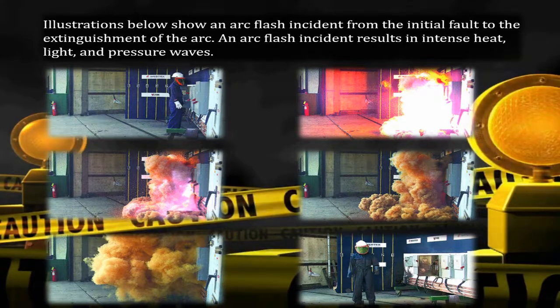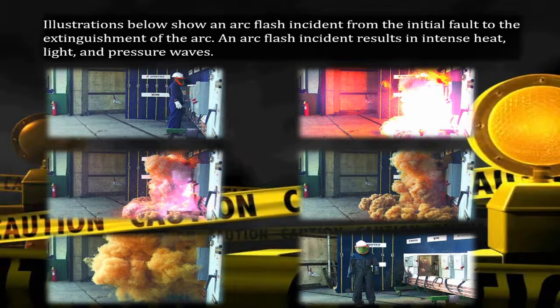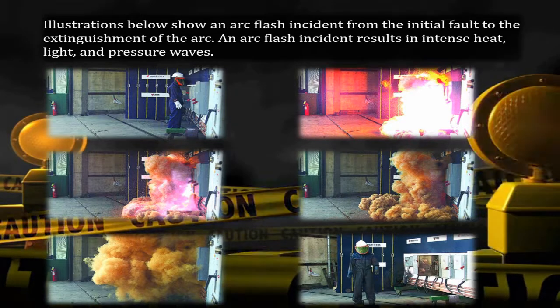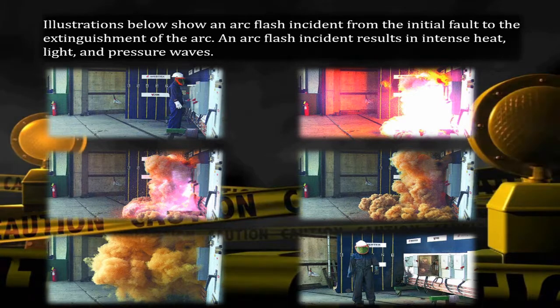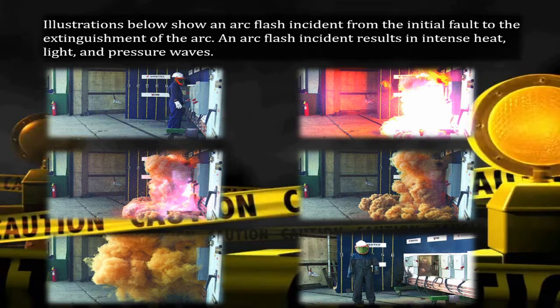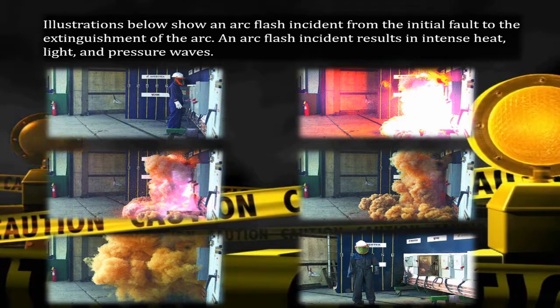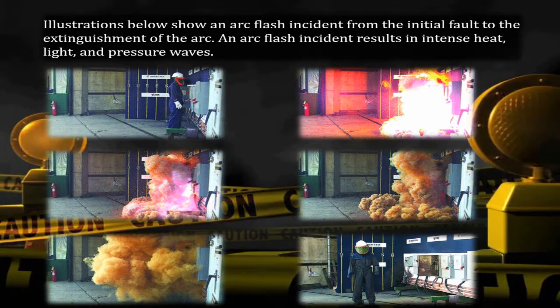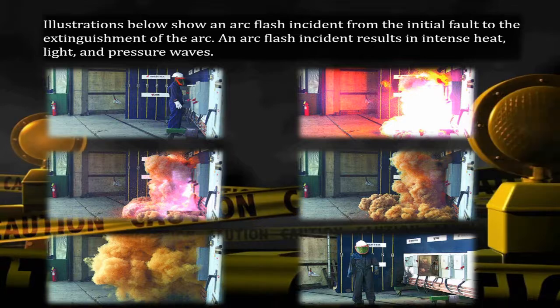Okay, this is out of NFPA 70E. And you look at this sequence of events here. It shows an arc flash from the initial fault to after it's been extinguished. The initial fault happens there in picture number 2, upper right hand corner, and it's ugly. It's really a huge amount of heat, molten metal, probably shards of metal and gases, a huge pressure wave, all the way down to the last picture there, which shows that this individual may have made it because of the personal protective equipment that he was wearing.